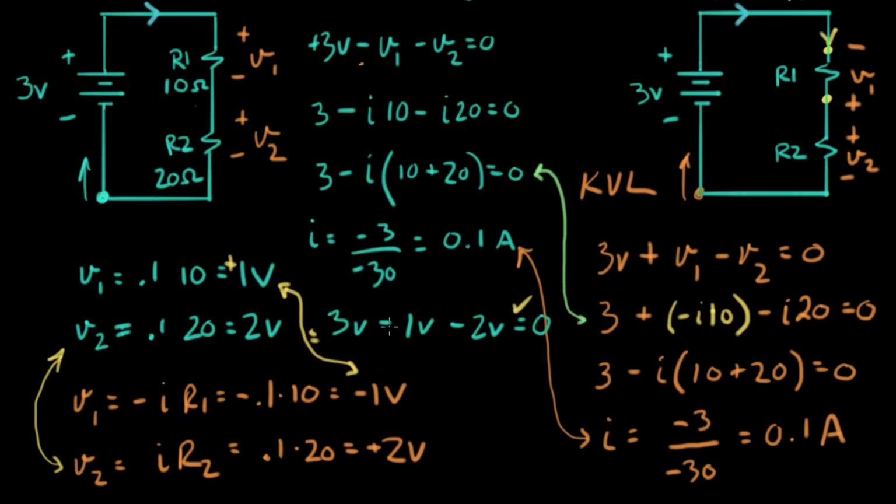So the purpose of the demonstration was just to show you that no matter which way you name the voltages, somewhere in here, like right here, Kirchhoff's voltage law will take care of keeping the sign right, and you end up with the same answer at the end. So when you're faced with a problem of labeling a circuit like this, don't stress out about trying to guess ahead what the sign of the voltage is going to turn out. You just need to pick an orientation and go with it, and the arithmetic will take care of the positive signs and the negative signs.